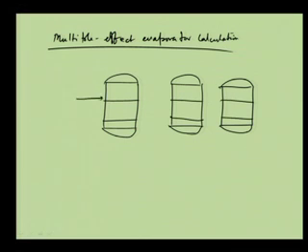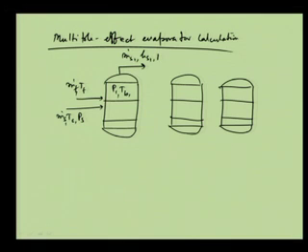So, this is the feed that is coming, m dot f, T f, and this is the steam that is coming, m dot s, T s, and then P s, the pressure of the saturated steam. And here P 1 is the pressure, T b 1 is the boiling temperature, and this is the vapor that is coming, m dot S 1, with H S 1, at a pressure of P 1. This vapor is coming as steam fed to this, and the bottom product is going there, and it is coming as a feed over here.